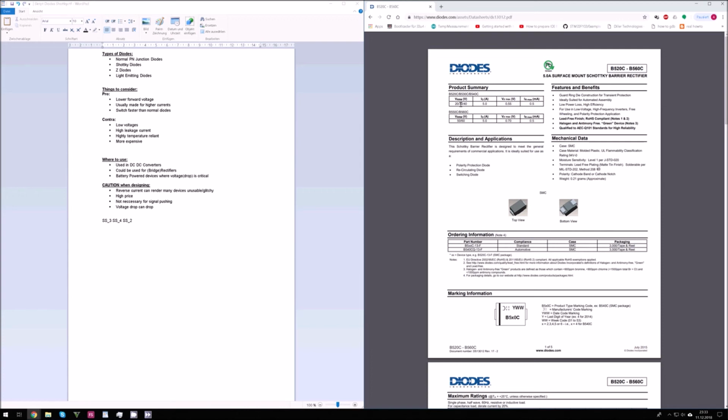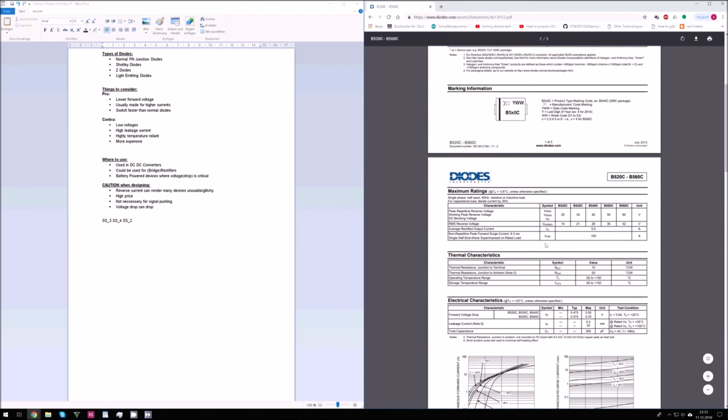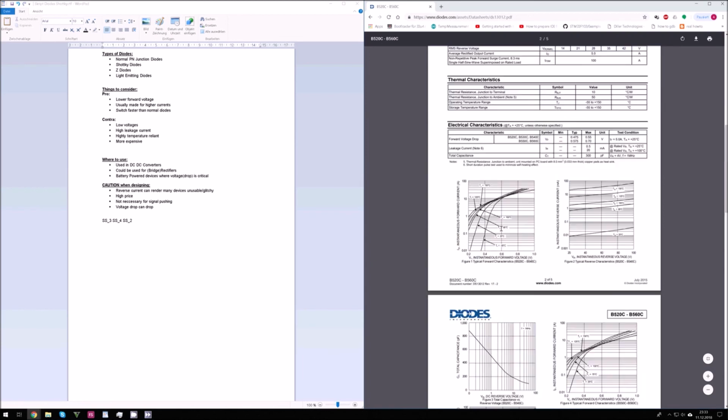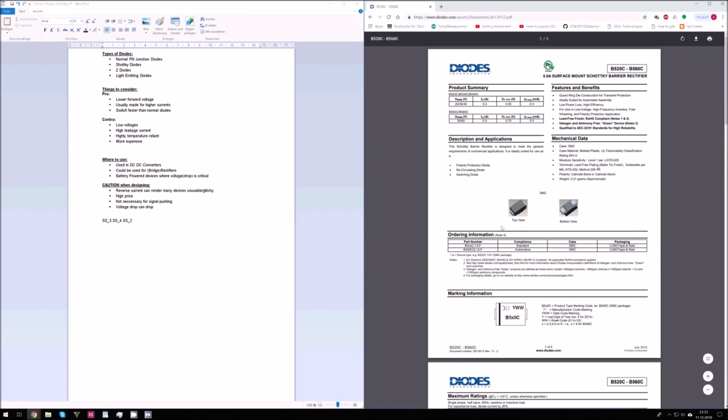You never engineer down to the facts in the datasheet on the top of it. You dive more into it and find out that your device, or the diode you use, is probably not as good as it is marketed on the first page. This is not with this company. It has nothing to do with the company. Many companies produce this exact diode and other parts which follow the same scheme. Just don't get tricked by just believing what's on the first page.